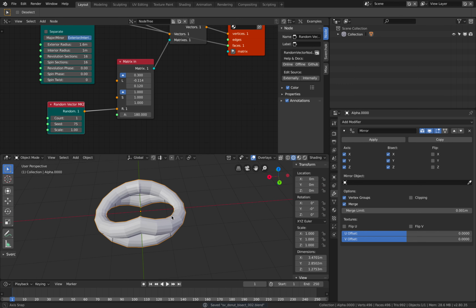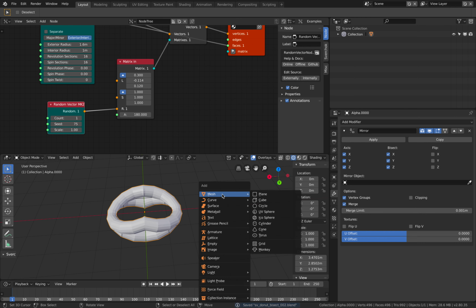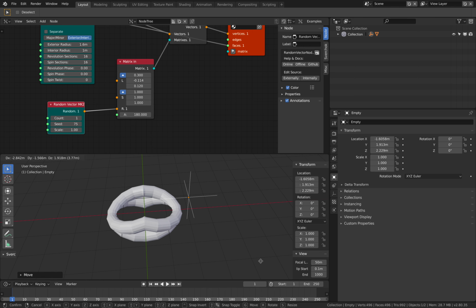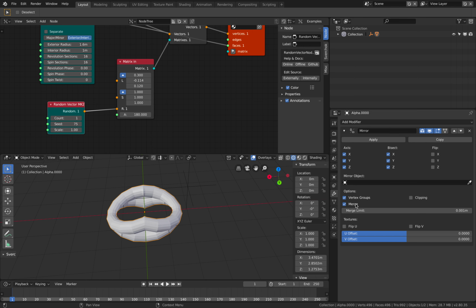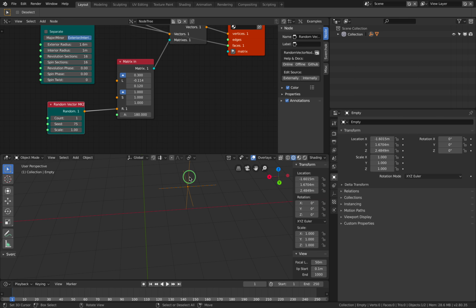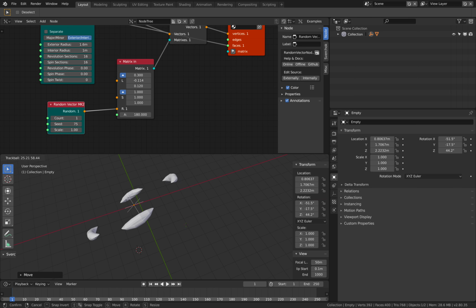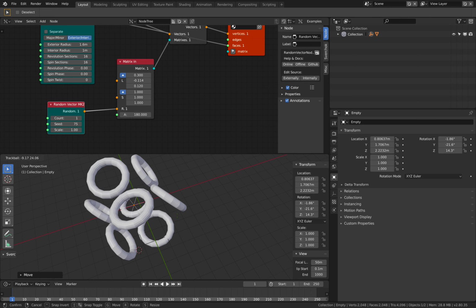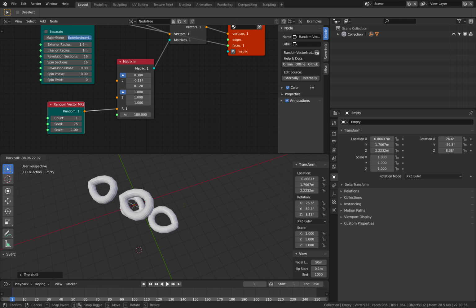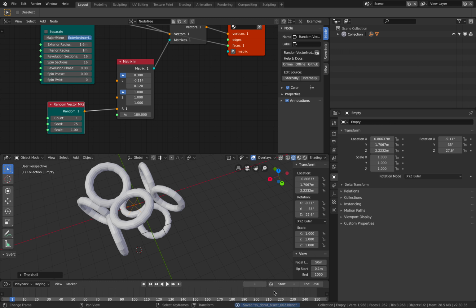Of course, with the mirror modifier, there's also these options to use a mirror object. So that's also really useful if you have an empty or null, and then you use the empty as another method to do the mirroring. That's also really interesting. You can animate it. This looks really cool, especially if you give it a matcap and it's doing it in real time.